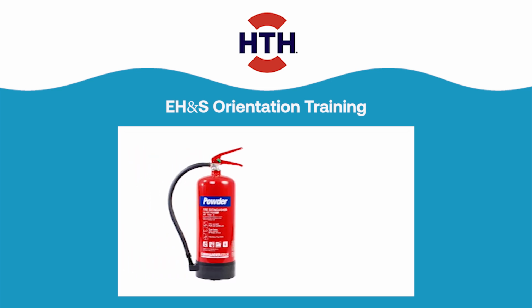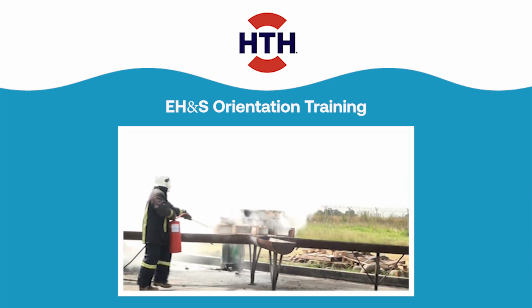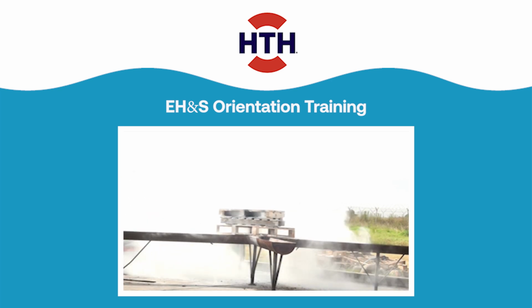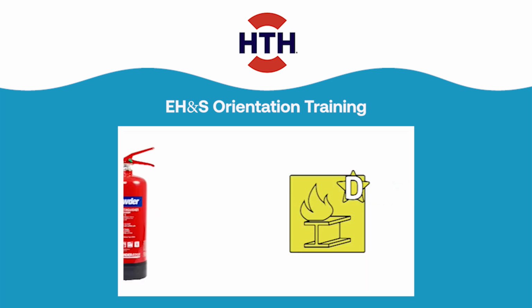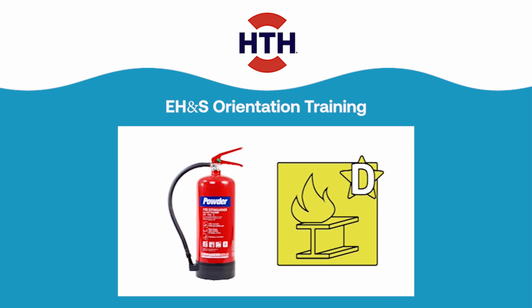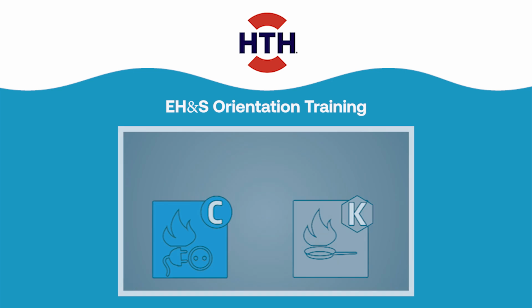Dry powder extinguishers are similar to dry chemical, except that they extinguish the fire by separating the fuel from the oxygen element, or by removing the heat element of the fire triangle. However, dry powder extinguishers are for Class D or combustible metal fires only. They are ineffective on all other classes of fires.